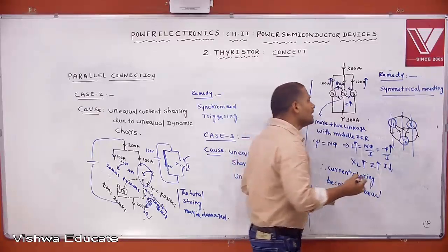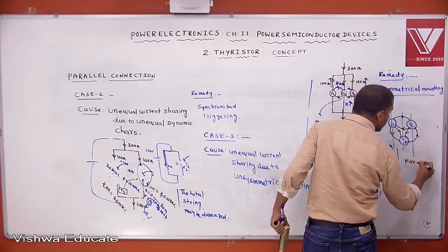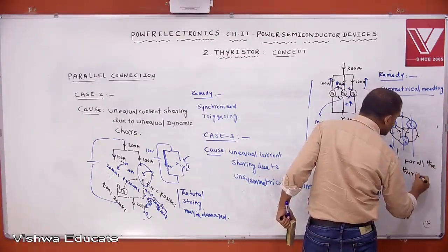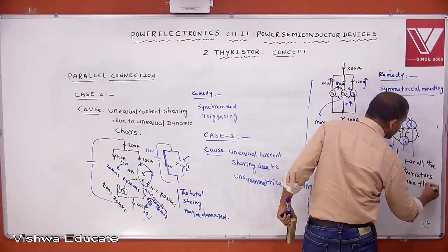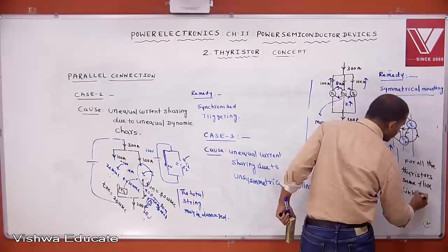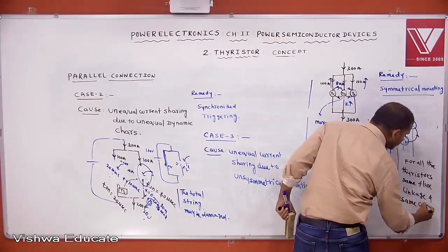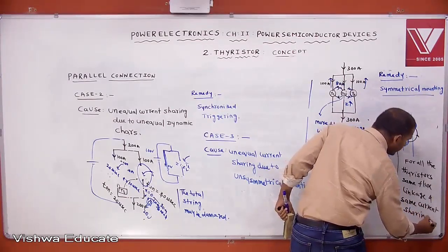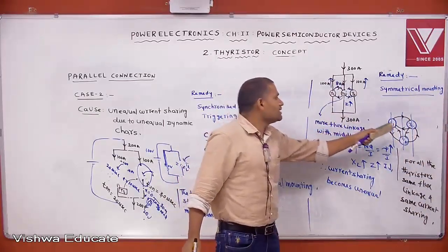Therefore, for all the thyristors, same flux linkage, and same current sharing. Okay, this type is called symmetrical mounting. This also parallel, this is also parallel.